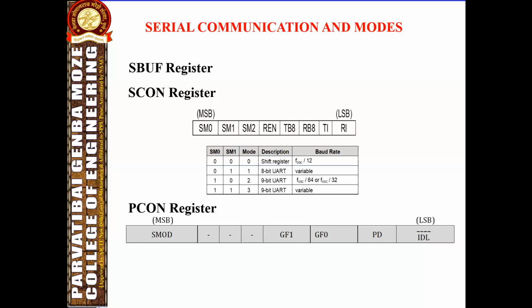The 8051 transfers and receives data serially at many different baud rates. The baud rate in the 8051 is programmable. A standard crystal frequency is used to generate the baud rate. The 8051 divides the crystal frequency by 12 to get the machine cycle frequency.